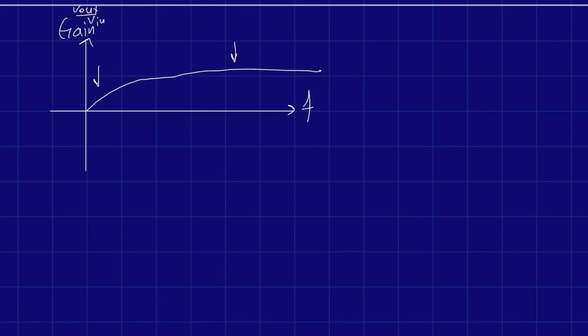But the problem here is that if you want to see, on the same plot, 100 hertz and 1 million hertz, you cannot do that, because here you would usually have something like 100, 200, 300. So 1 million is very far away. And that's where Bode plots come in, because you plot things on a logarithmic scale, and on the same graph you can have very low and very high frequencies.